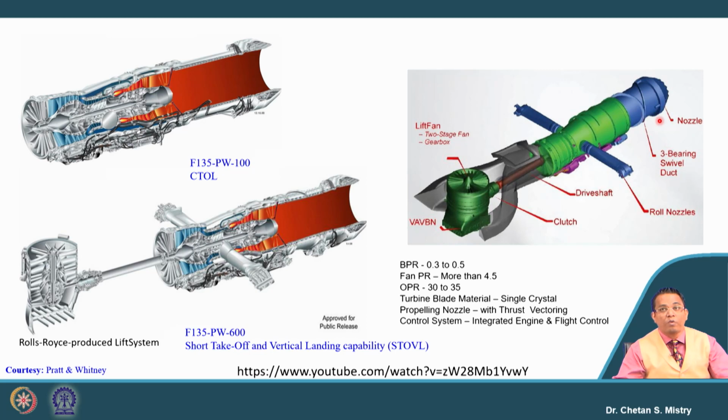So those who have not attended the second week classes, just go through that, where we have discussed the construction of nozzle, and there also we have explored some of the possibilities in terms of variable area nozzle. Here there is a shaft which has been connected with this fan configuration. This fan is a counter rotating configuration, that will be helping in terms of generation of the lift. So we can say by swivelling this nozzle downward, that will be giving the vertical takeoff, and in order